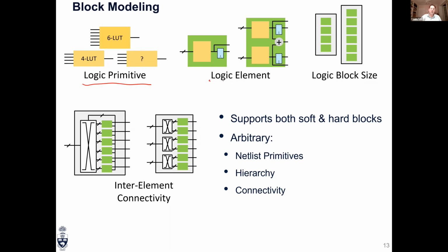You can combine those logic primitives hierarchically into larger physical structures. So you might have logic elements that combine a few lookup tables and registers. You might have logic blocks that combine several of those logic elements, and they could have local interconnect within them. And you can specify all of that. And it's not just for logic blocks. The same approach is used for RAM blocks, DSP blocks, and other things that don't really have a name. You're not limited to those types of blocks. So it's quite flexible in how you model the blocks.